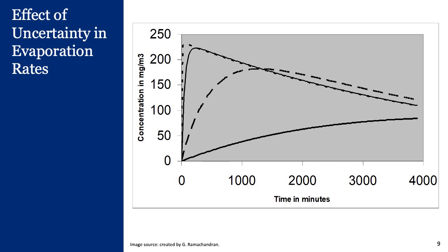So when alpha is 0.2 per minute, we have the profile that is shown by the dotted line at the very top. So we have a sharp spike right away, and then there's a slow decay over the rest of the weekend. And at the end of the weekend, our concentration in the room is about 108 or 109 milligrams per cubic meter.